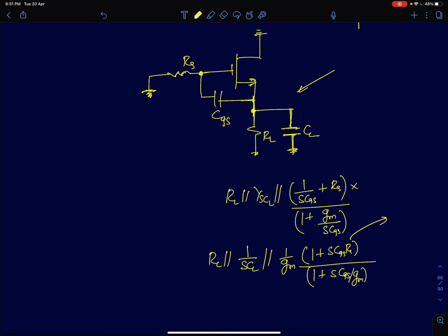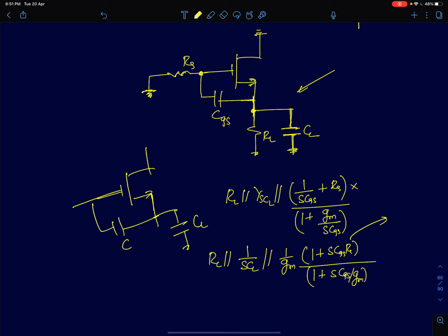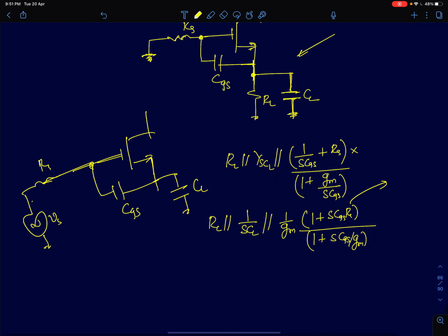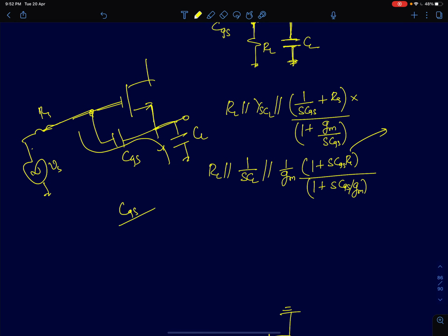Okay, but what we will do is look at how the circuit behaves at very high frequencies, which I have already analyzed. At infinite frequencies, it's going to behave like this. You'll have two capacitors, CL and CGS, and RS and Vs. Previously, if you recall, the current was entirely coming from Vi, so there was a direct potential division at the output. The voltage at the output was CGS by CGS plus CL times the input. But now there is also RS.